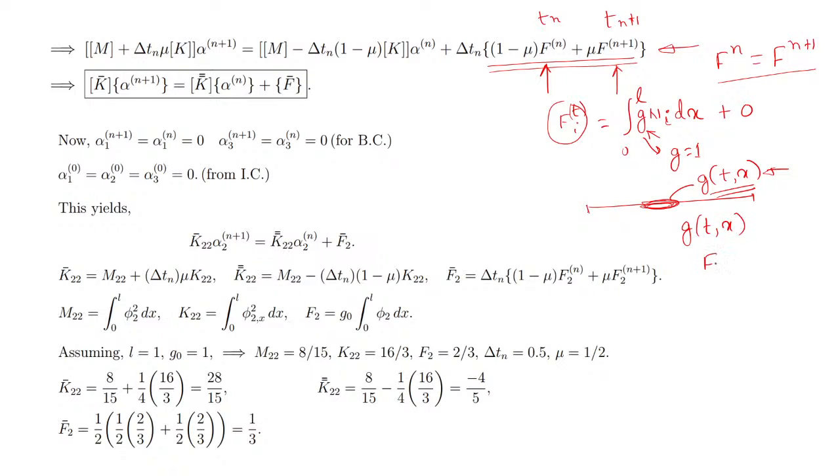So if I want to calculate fi at time tn, I have to evaluate this function at time tn and at the Gauss points, xg. So I have to evaluate this function at a particular time instant. In that case your fn and fn plus 1 will not be equal. But for this problem your fn and fn plus 1 are the same. So you are heating the domain with a constant heat source, and initially the temperature was 0 everywhere, and suddenly you have switched on one heating element, so obviously your temperature is going to change with time.